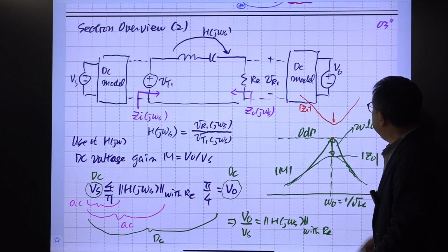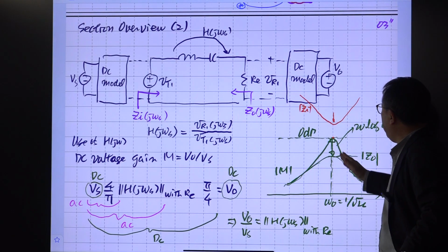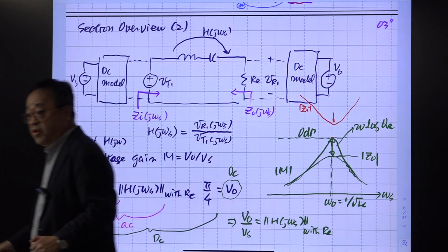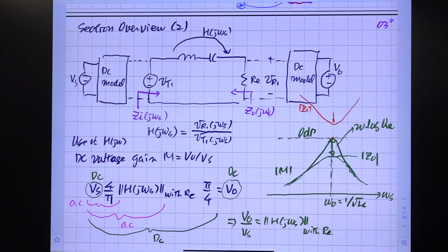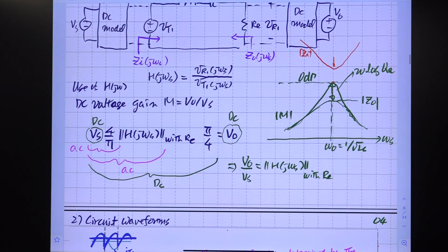Okay. So you don't have to watch this. You just watch this voltage gain. If voltage gain is declining in some region, then the converter is in GBS operation. Otherwise, the converter is in GCS operation. Okay. So that is the result. Erickson spent 20 pages to explain this. Okay? I did just 2 pages. Basically, the same thing. Right? He used some different notations.